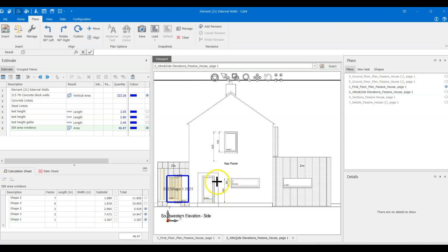1662. A good thing about this as well is it gives you the stated dimensions. So when you go back to check your lintels, you have the length and you just add on the bearing. Mine is set up, by the way, yours may not be set up to display the dimensions. I had to go back and put that in somewhere. I think it might be in view or data. Play around with your settings.